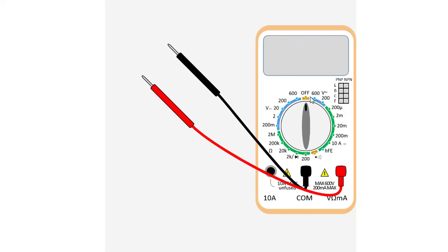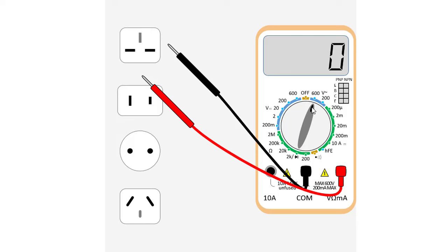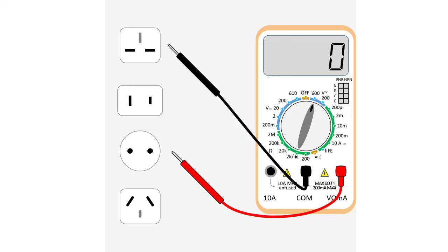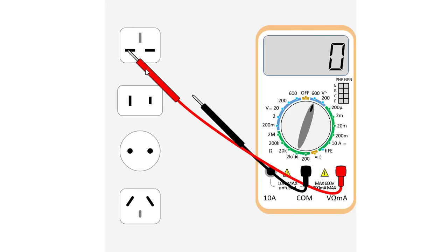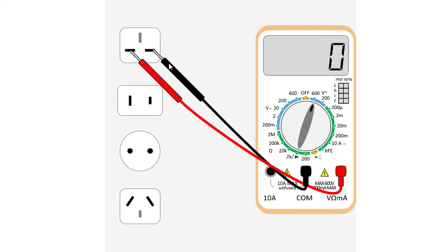So let's start with AC voltage. So we will take this knob here. Now here we can see, we have to insert these probes here. This red probe is for positive terminal and this common is for reference or negative terminal. But here we are currently measuring the AC voltage, so we can put any probe any side. So let's put this probe this side and this probe here.